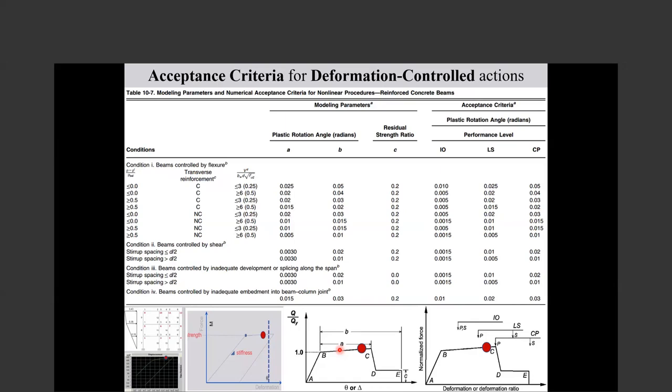Some of them give you values like 20%, 15%, 10%, that if you pass the limit for the drift or the limit of the stress ratio, if you are doing nonlinear analysis, it's okay. But anyhow, they ask that the results be approved by nonlinear analysis.